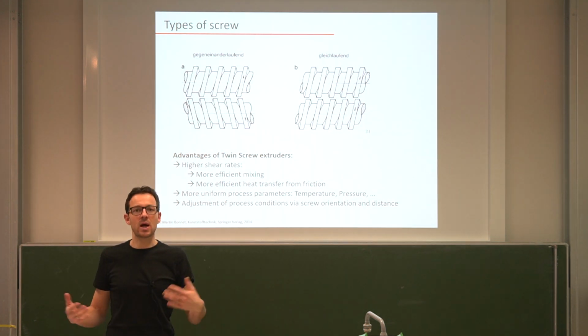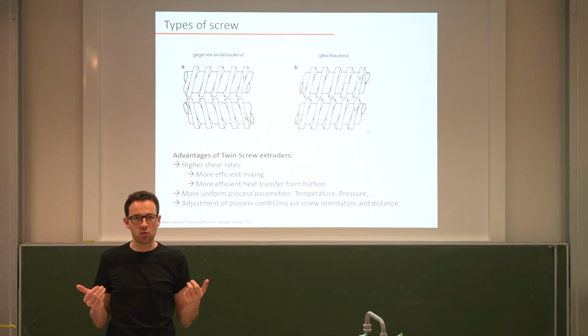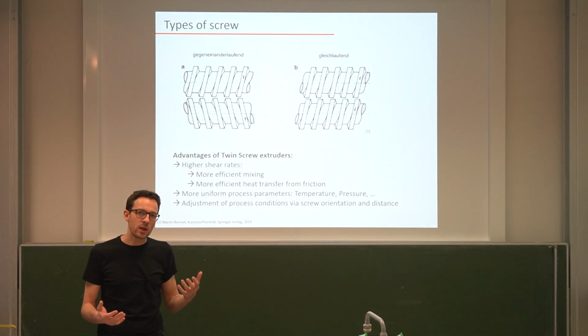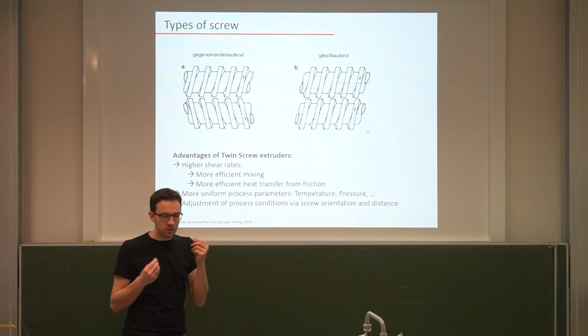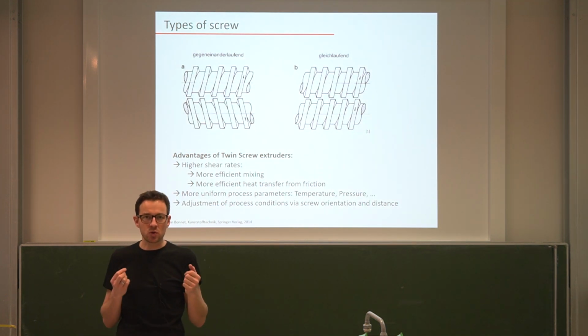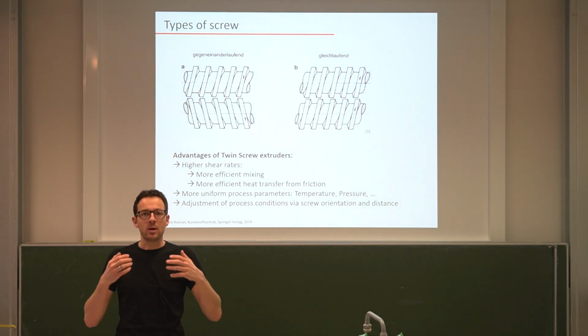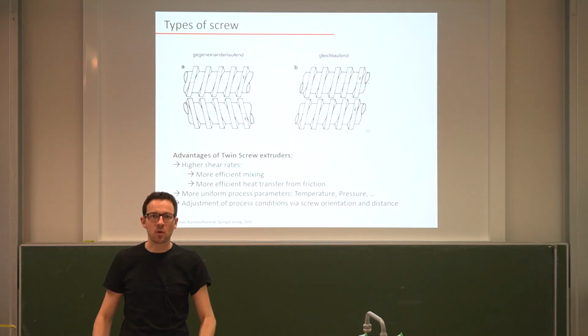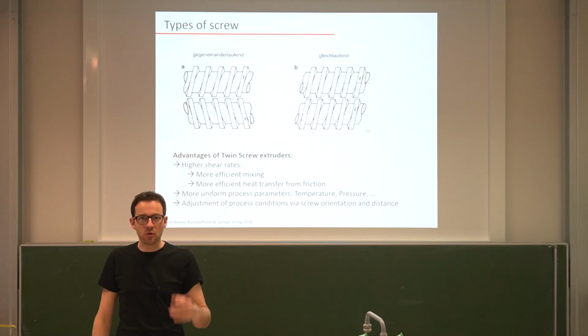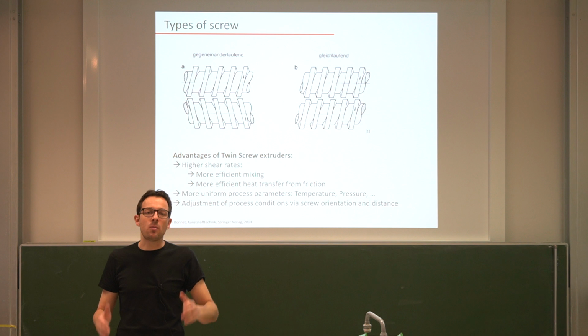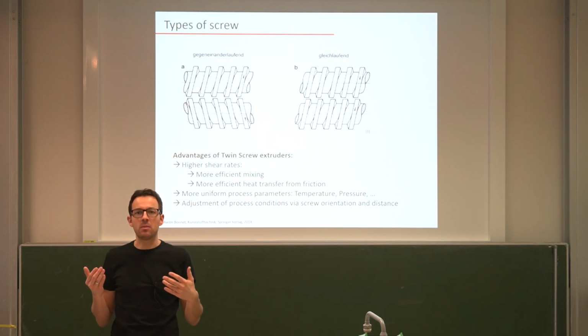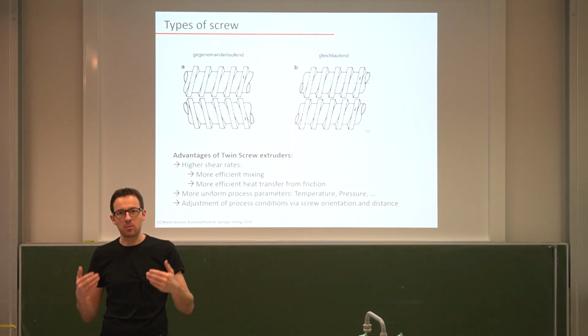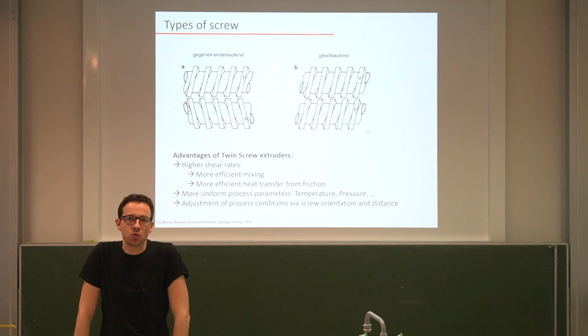And that means that there is hardly a one-size-fits-all extruder that can process any type of polymer. What you need to do is delicately balance the friction that you supply, to either be very mild when you have polymers that tend to melt or become soft very easily, or to apply more and more friction for polymers that have a higher glass transition temperature and therefore are more resistant to becoming soft.